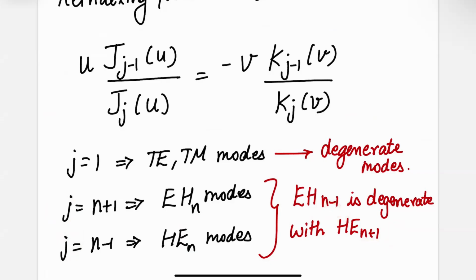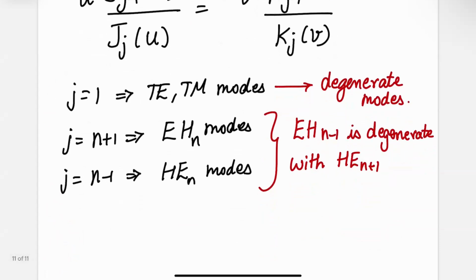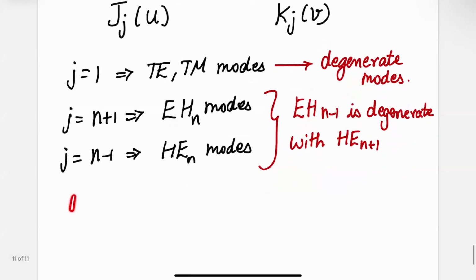Okay? So what does it mean when you have so many degeneracies, right? You're ending up with these solutions which are essentially like plane waves, which means that if I have a plane wave, it's neither EH nor HE. And since it's kind of a homogeneous medium, we said that these LP modes are very similar to TEM or plane waves. We'll see what they exactly look like, which means they should not have any Z component.